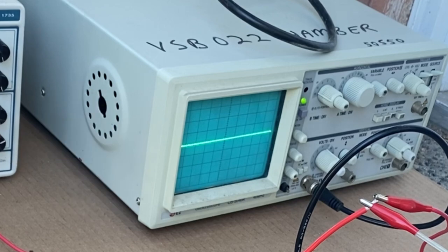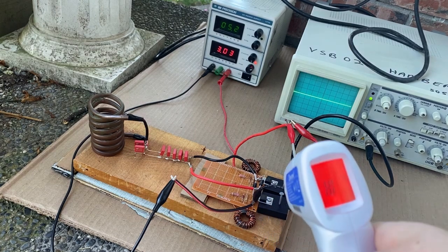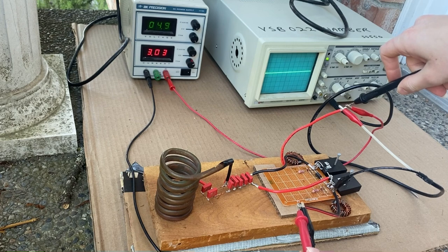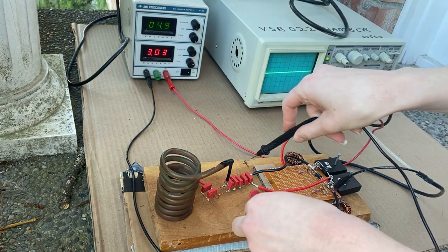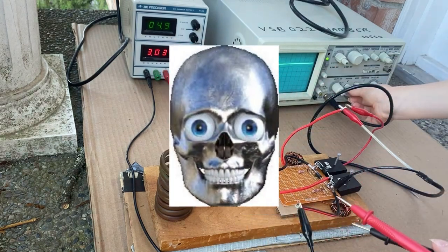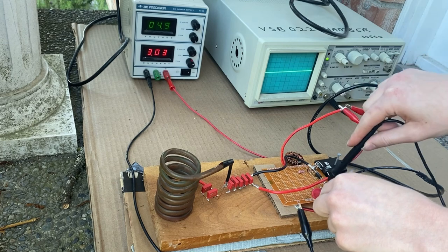The oscilloscope only displayed a flat line. I thought something was wrong with the connection wires, but I noticed the heat sinks became very hot. I used a multimeter to measure voltage and confirm the fact that my circuit was not oscillating. It read 0 across the capacitors and work coils, so clearly something needs to be fixed. I will figure this out sometime in the future.